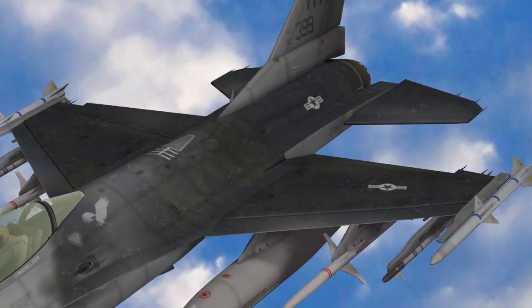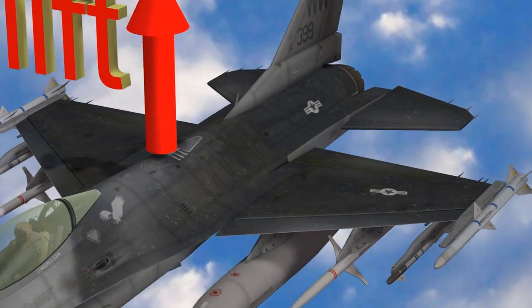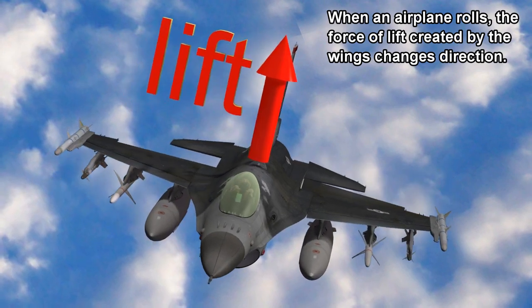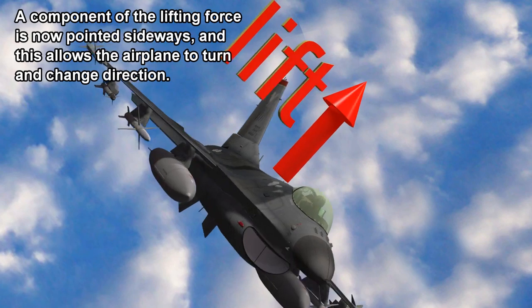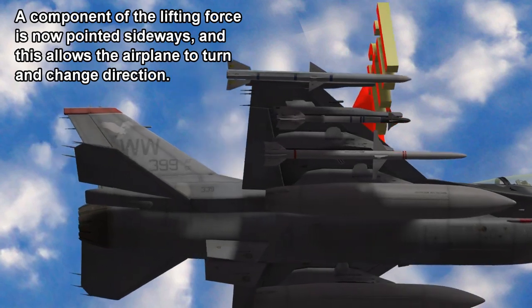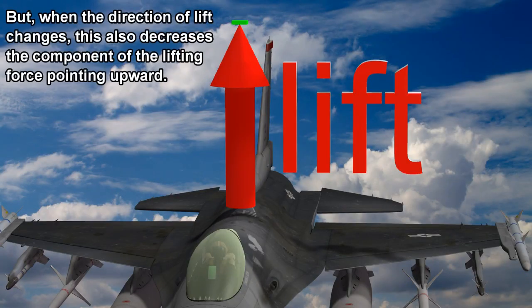When the aileron on one wing goes up, the aileron on the other wing goes down. When an airplane rolls, the force of lift created by the wings changes direction. A component of the lifting force is now pointed sideways, and this allows the airplane to turn and change direction. But when the direction of lift changes, it also decreases the component of the lifting force pointing upward.